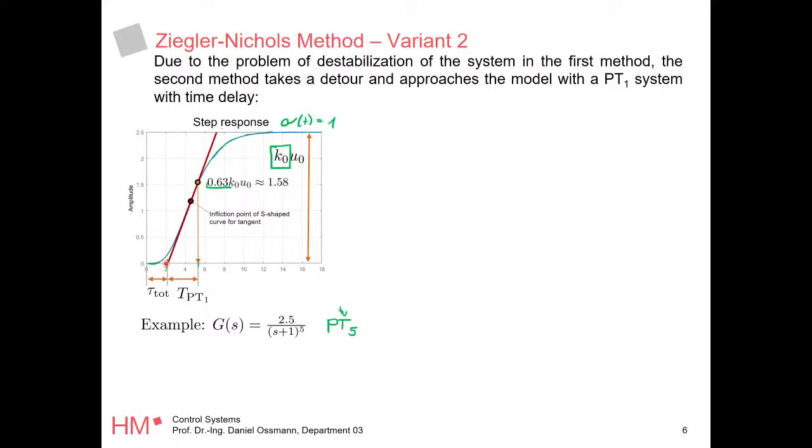And in system dynamics, we will go into that a little bit deeper. This then looks like an exponential function multiplied to your transfer function. Okay, so if you look closely, this is about 3.5, these are 3.5 seconds here. We've got a gain of 2.5, and we say our pure time delay is about 2 seconds. So from here to here. And then this is our system approximation.